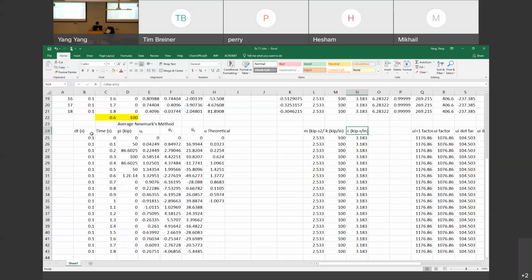So we use the same mass, K, and damping ratio here to start. Now on the left side, if we use the numerical method, since we have already derived the formulas to calculate the different responses here, we use delta t equal to 0.1 second. At time 1 and time 0, we have the data for the force.